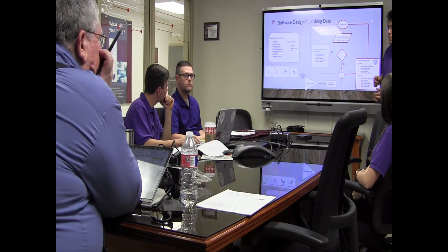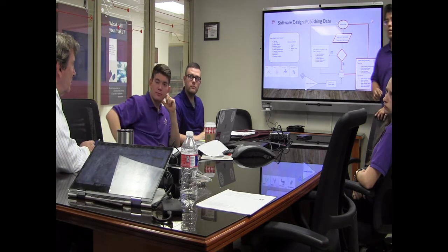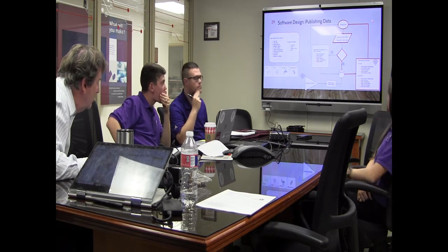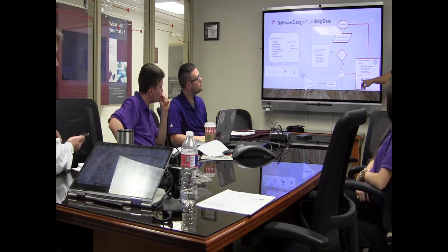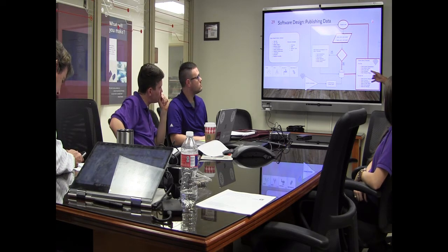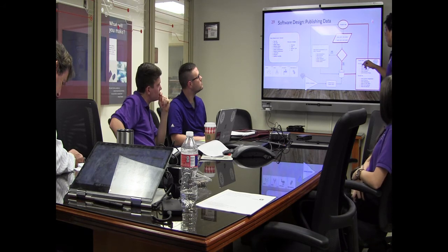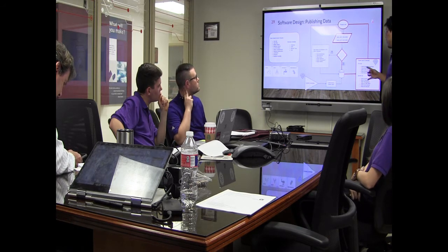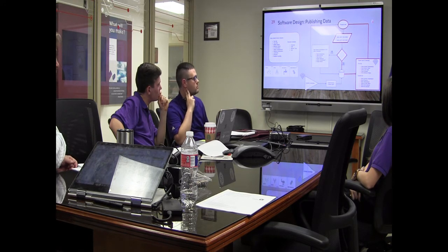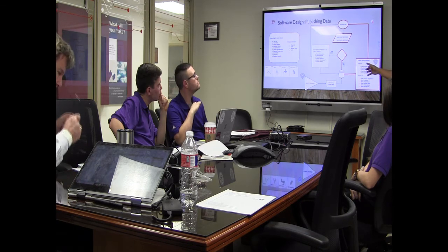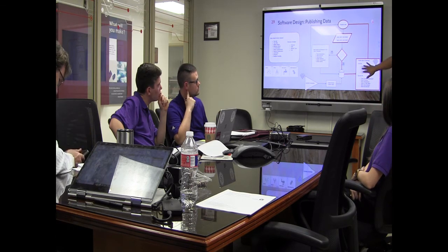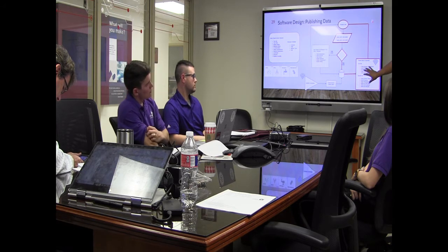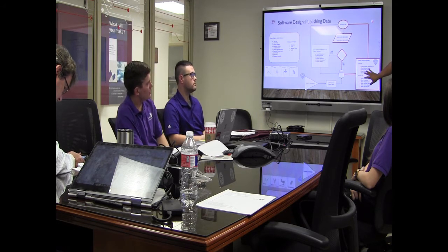Oh, that's the flaw. Now I'm wondering if you really can fix the flaw in the motion sensor. Well, in this case, I have send desired temperature in both sides, in both sets. Also, this is 5 seconds, which I could easily reduce to 2 seconds without overloading Cayenne. This was my safety number because I just wanted it to work the first time around. But the limit is 10 write statements per second, so this is double the timing that we're waiting.